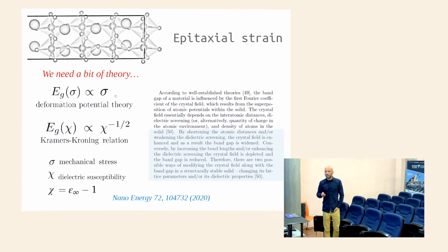But also, there are other ways that have to do with electronic screening in the material that may also have a strong effect on the energy bandgap. In particular, by shortening the atomic distances or weakening the dielectric screening, the crystal field is enhanced, and as a result, the bandgap is widened. And conversely, by increasing the bond length or enhancing the dielectric screening, the crystal field is depleted and the bandgap is reduced, right?